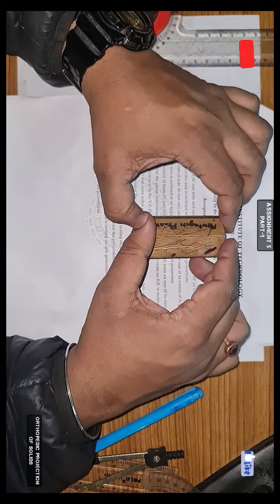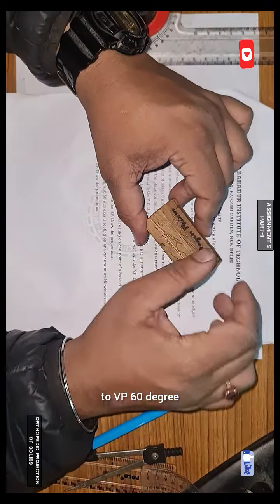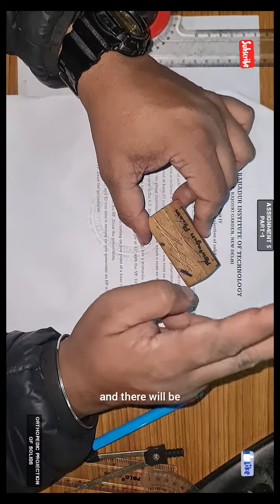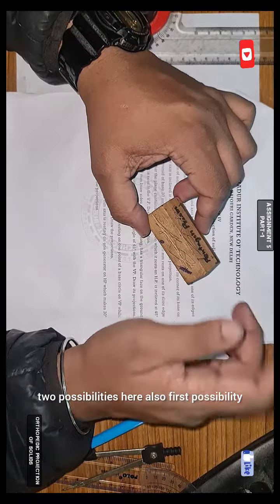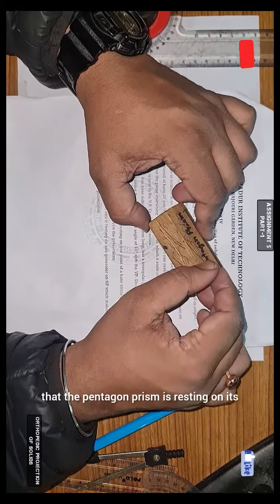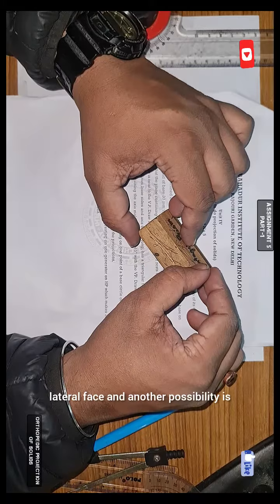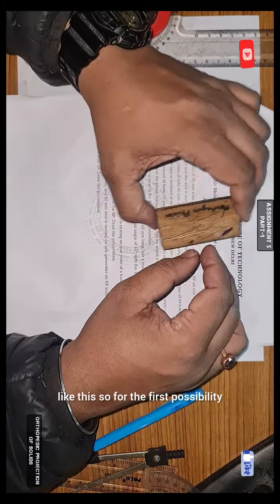Then you have to rotate it to VP 60 degree, and there will be two possibilities here also. First possibility that the pentagon prism is resting on its lateral face, and another possibility is that it is resting on its lateral edge like this.